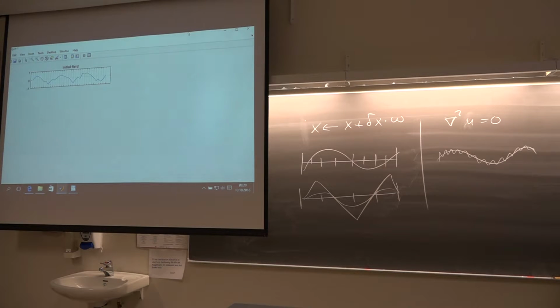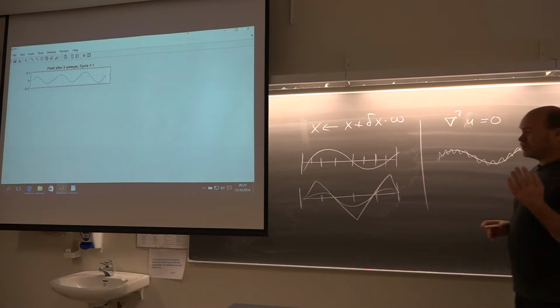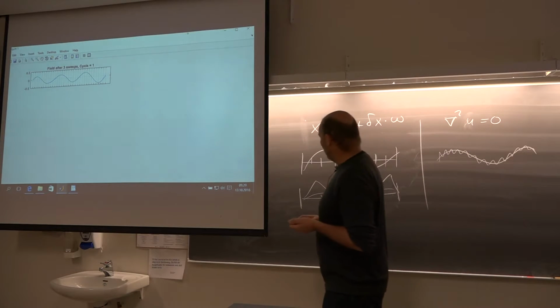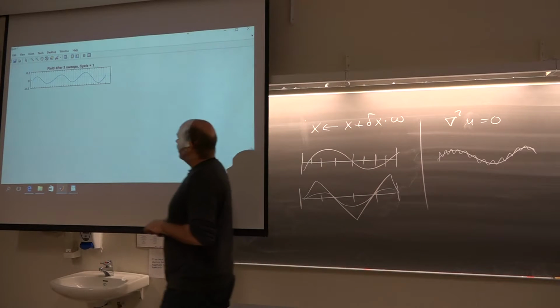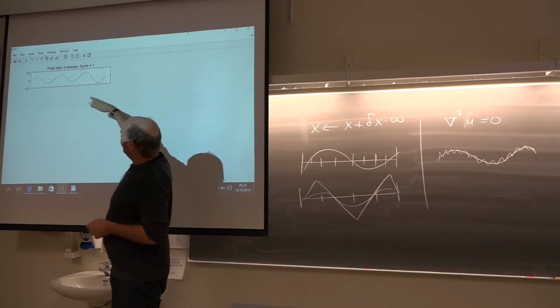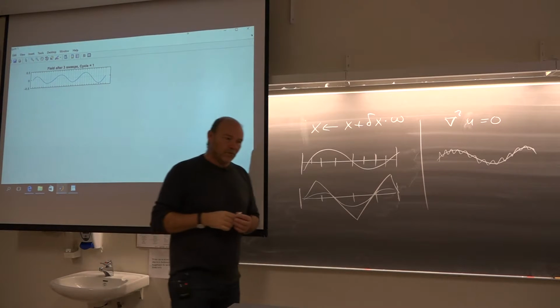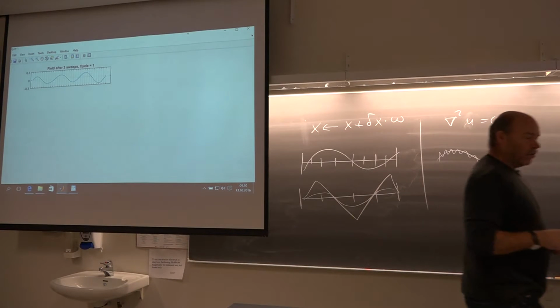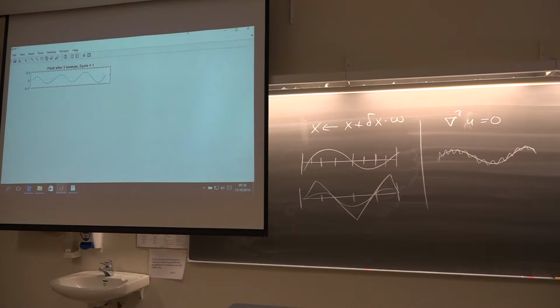So now with Multigrid, we do just 1, 2, or 3 iterations with these classical methods, just to smooth out all the high frequent noise. Now we have a very smooth solution. It's still wrong, of course, but now it's very low frequent, meaning if we had continued here with this fine mesh with the Gauss-Seidel iteration, or with TDMA for that matter, it's going to take forever.